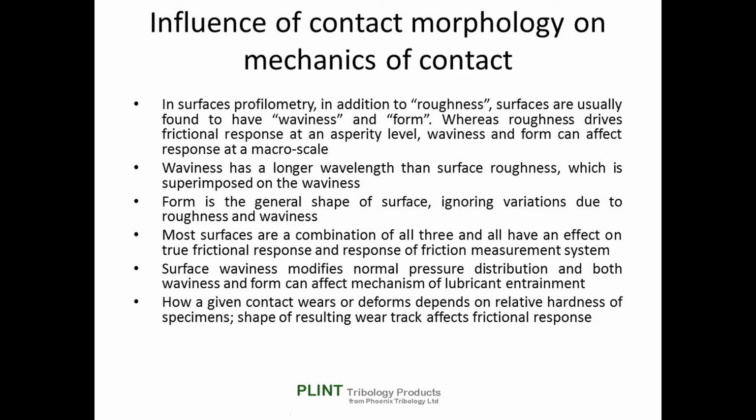In surface profilometry, in addition to roughness, surfaces are usually found to have waviness and form. Whereas roughness drives the frictional response at an asperity level, waviness and form can affect the response at a macro scale. Waviness has a longer wavelength than surface roughness, which is superimposed on the waviness.